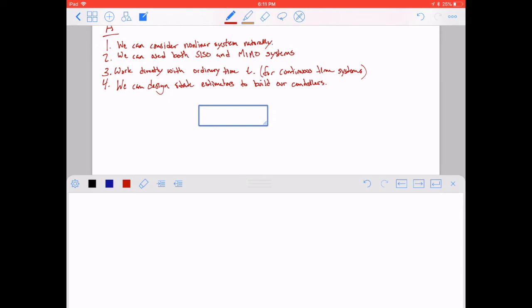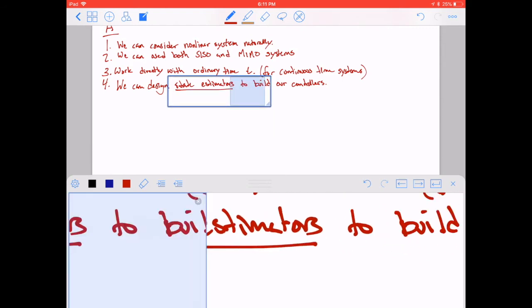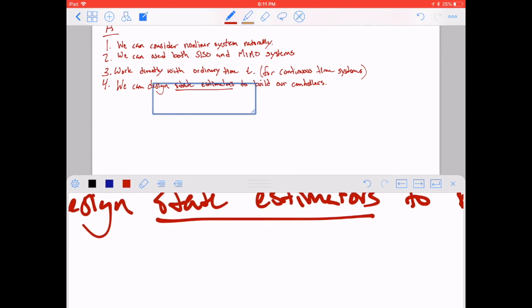And now you say your reference temperature is the temperature that you need to be. I think it's like 170 degrees or something like that. It's been a while. But now, instead, you can take the estimate and compare it to that reference and then drive that power input that you want. Okay? So that's what I mean. Doing that is a state estimator. Converting the voltage measurement into a temperature, right? Knowing the dynamics of your system, knowing the output matrices and conversions, you can do that quite easily. And that's pretty simple to do.